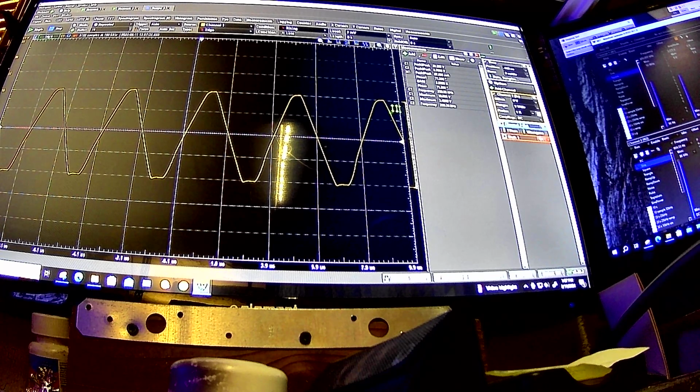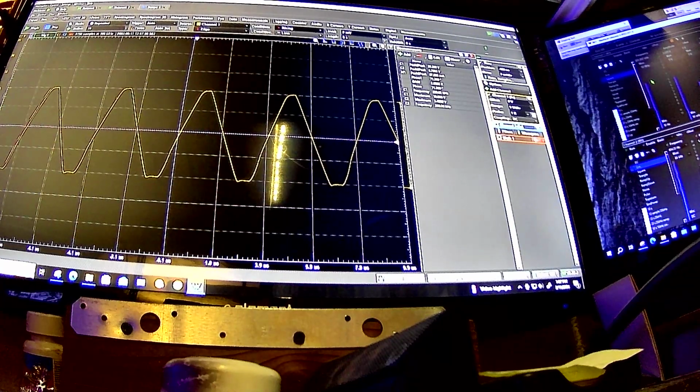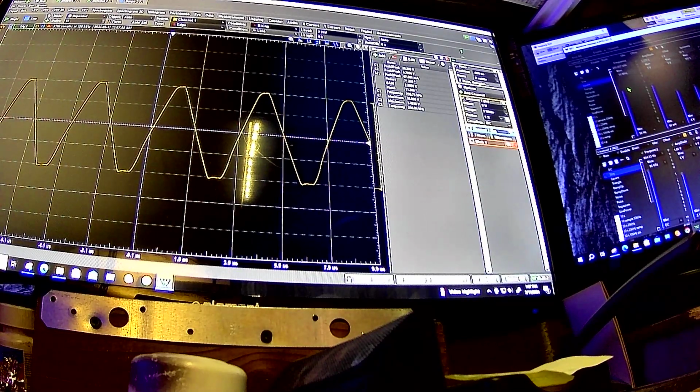So I've got a loop gain available of about 10, at this closed loop gain of 3, so you're still going to get fairly linear behavior. Actually, I have it set to 250 kilohertz exactly right now. That's what I was setting for this test.